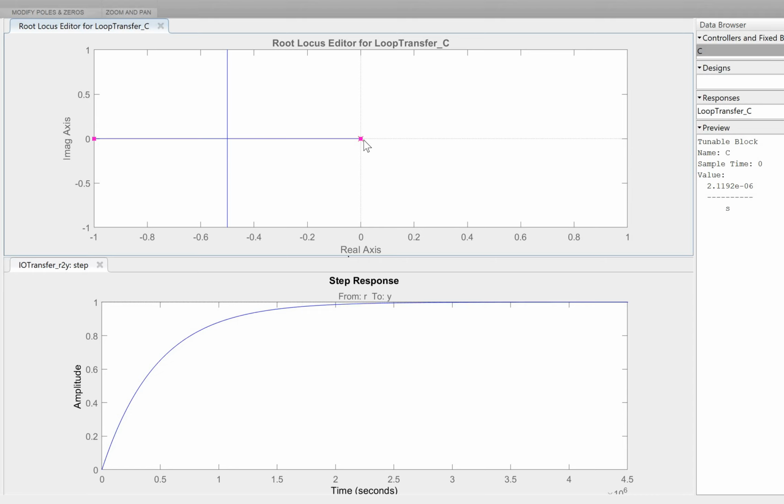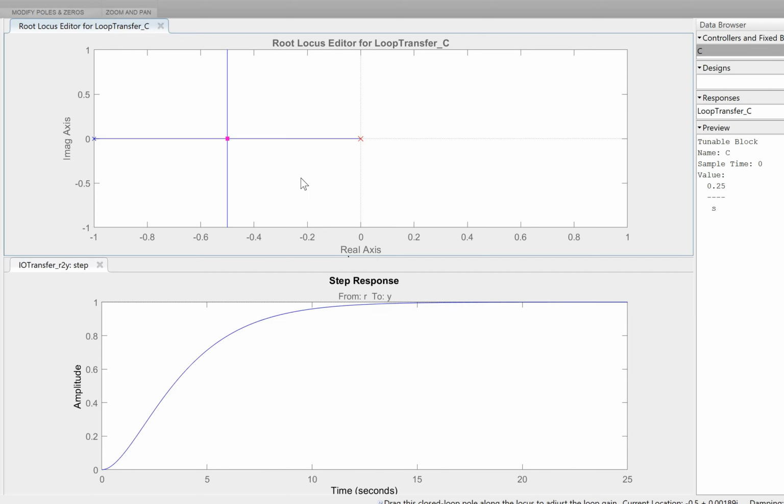And now I can increase my gain and improve the performance of it a little bit. And if I come in here to critically damp, that's the best I can get without an overshoot. But I've always got a zero steady state error with a step input for this first order system with an integral term in my controller. And so it's a very nice feature if you're looking to reduce the steady state error.